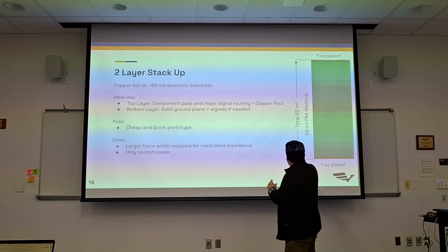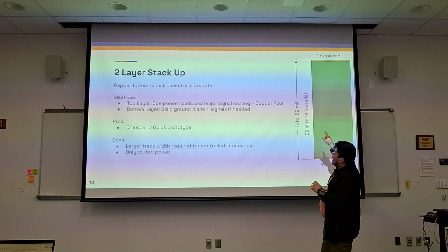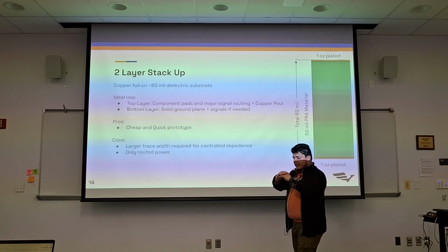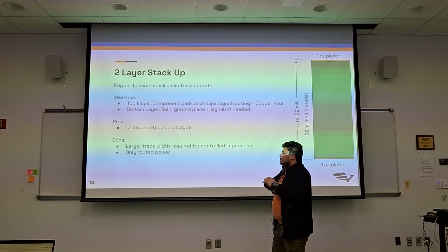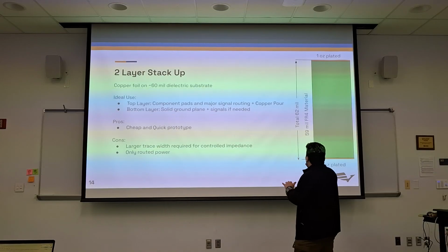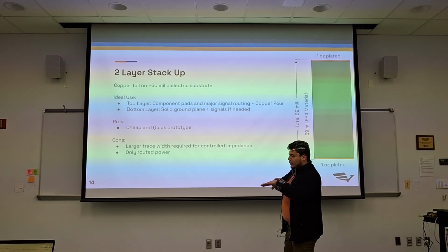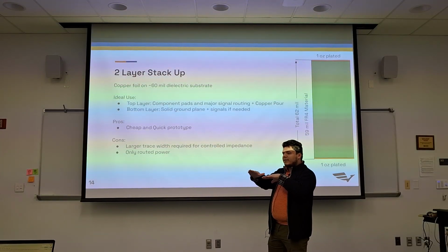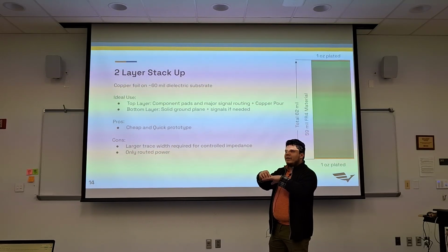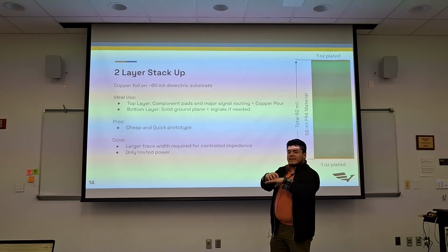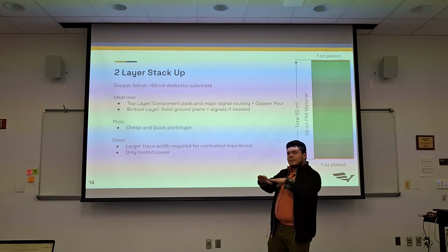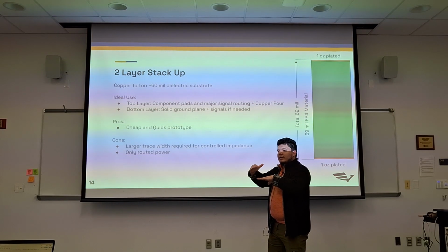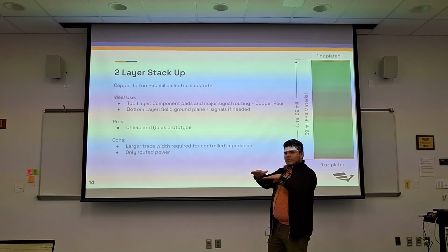But when we're talking edge layers, since we have copper pads that we want a certain adhesion to, what the manufacturers do is they actually do about half of the thickness, give or take, and so they etch the copper in this case, 1/2 ounce, and then they plate over so that your final thickness is 1 ounce.